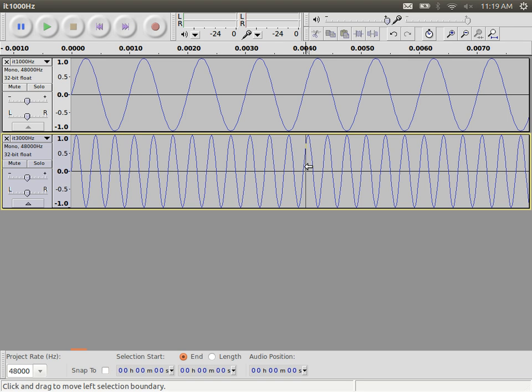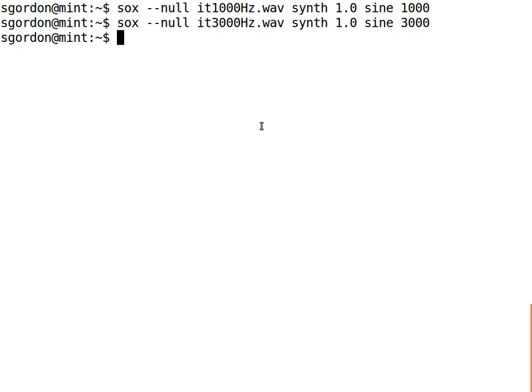And now I want to combine them, because our equation, our signal, is the addition of those two. With one small exception, the second component should have an amplitude 1/3 of the first component. In these plots, the amplitudes are the same. So what I want to do is mix the two audio files, and at the same time reduce the amplitude of the second one. And SOX can do that for me as well. It allows us to mix audio. If I remember how to do it.